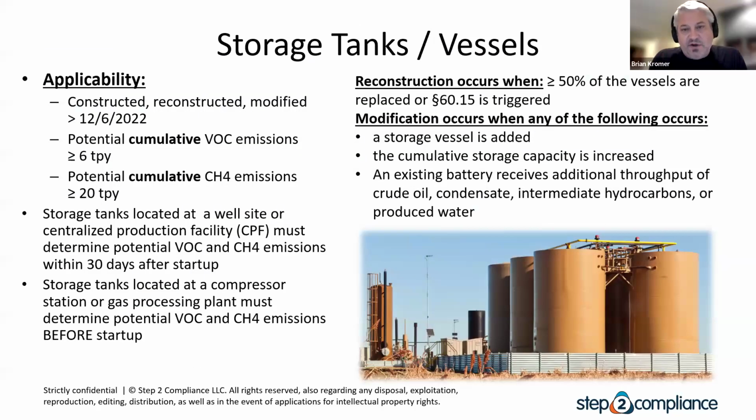And one last comment on the pneumatic controllers. It does not mean they can't run off process gas, or that they must be retrofitted to something like electric, or that they must be 0 vent. So it's not forcing you necessarily to remove or change those controls, but to address how they vent. I've heard some people say that it has to be electric, or process, or compressed air or nitrogen, but no, you can run them on process gas, you just can't vent.